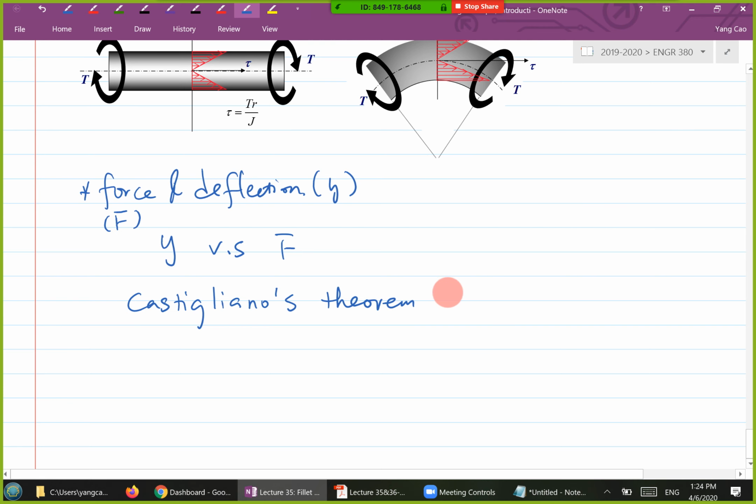Overall, based on this theory, you get your deflection y is approximately 8 times F times D cubed times Na over d to the power 4 times G. What are they? F is the load, capital D is the spring's mean diameter, d is the coil diameter, and Na, this is where you have to be very careful, is the number of active coils, not the total number of coils, and G is the shear modulus.